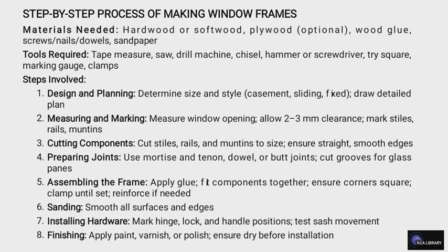For the window frame, the materials and the tools are also important, and the steps include design and planning. Then you do the measuring and marking, where you measure the window opening and allow for 2 to 3 mm clearance, and also you cut the components. After cutting the components, you prepare the joints, just like the door.